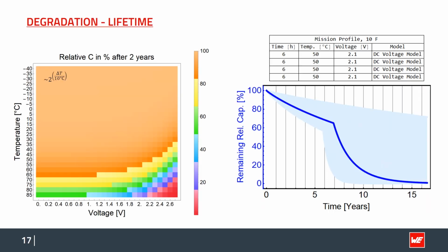Another important aspect to consider is the lifetime. For supercapacitors, it might not be suitable to think in terms of lifetime, but in terms of capacitance degradation. Since you may have certain tolerances for your required energy capacity, you may also have the opportunity of oversizing your layout to compensate for certain degradation.